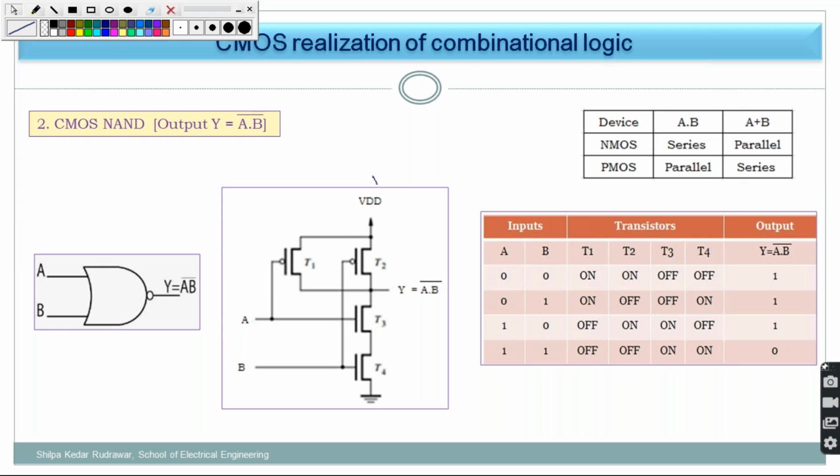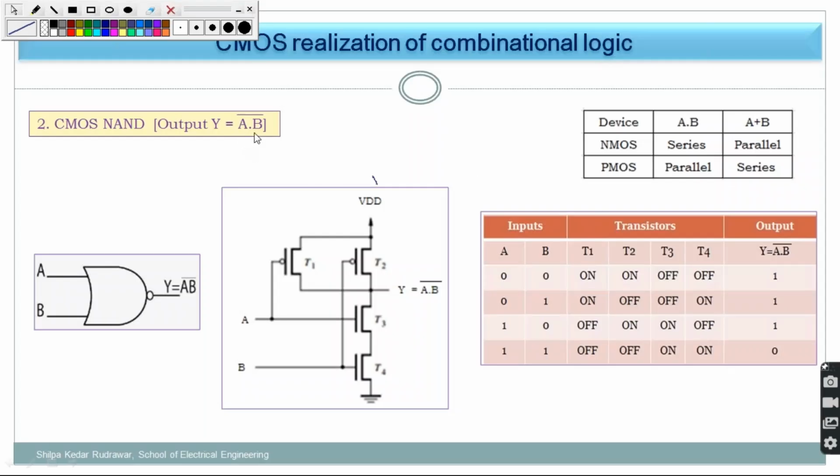Okay. So what is meant by that inverted logic? If I have written here, it is written as A into B complement. Now you should know the things properly. Implement this NAND gate. So NAND gate is defined by this equation. So first step is to write the equation if that is not given. So here the equation is A into B whole complement. Now you know that A complement into B complement is totally different from A into B whole complement. That's De Morgan's theorem, just remember. So here A into B whole complement is given.